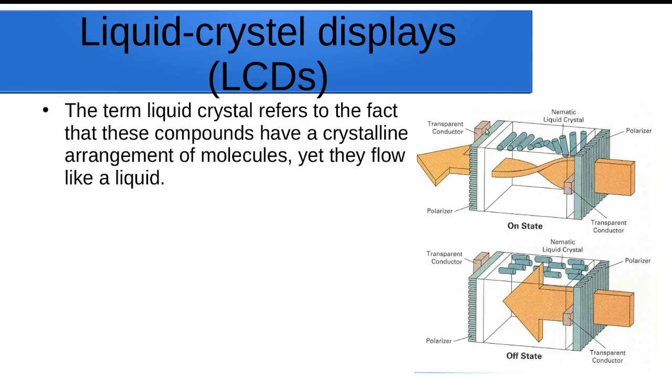Now you understand the job of these conductors. Wherever the conductors intersect, it means a particular pixel. At that position, the liquid crystals are there, showing the path for the light. The light comes through the vertical polarizer. It should go vertically, but these crystals make it twist.